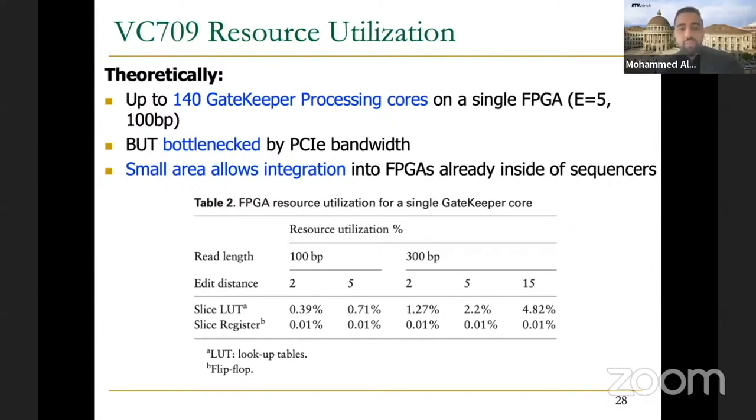You may want to pipeline these problems together because the maximum delay you can have cannot achieve the maximum frequency you can use in the FPGA. So the critical path in FPGA implementation is very important here, so that you can drive a lot of these gates in parallel.